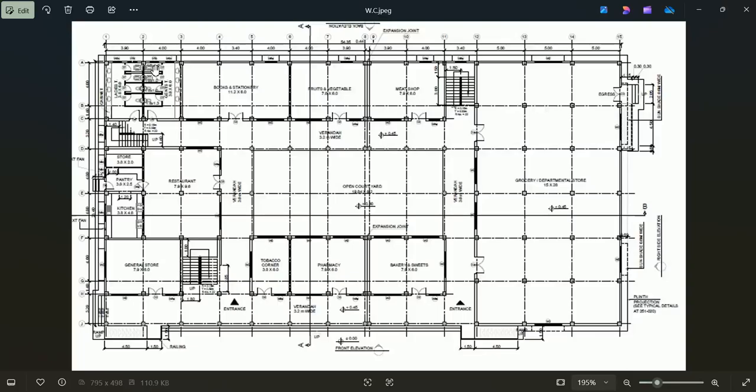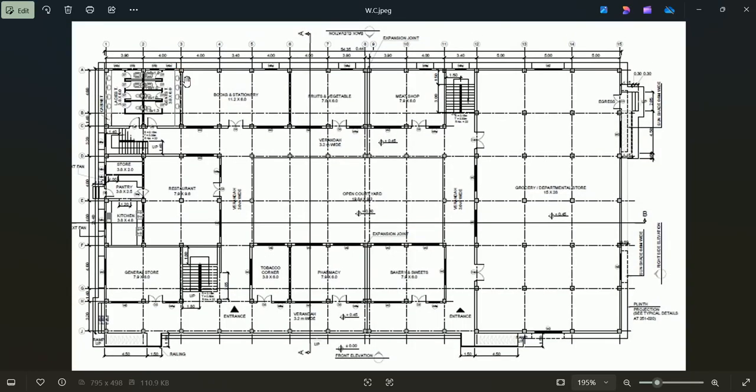Normally we are doing a frame structure, and in our case we have a frame structure, and we have to provide columns, not too many columns on one side, like a lot of columns on this side and a lot on this side, while the intensity of columns is less on that side. It will not be good because of the disturbance of rigidity.